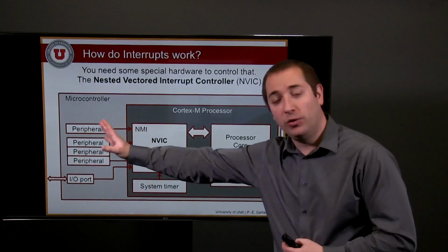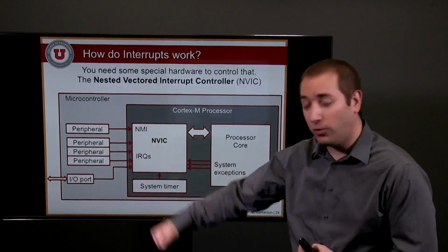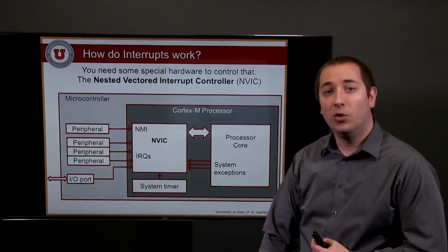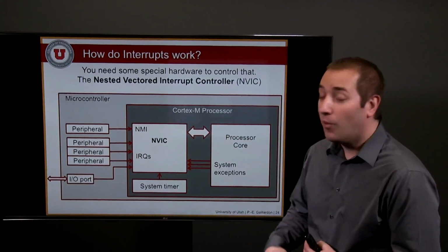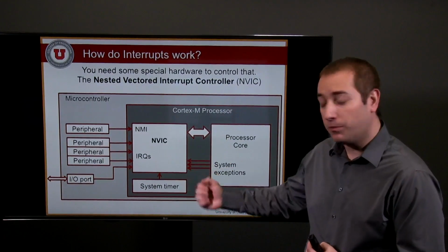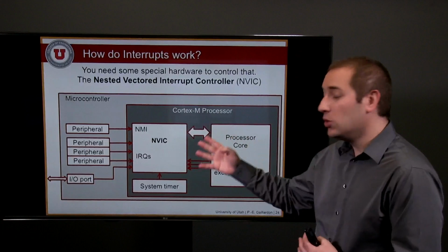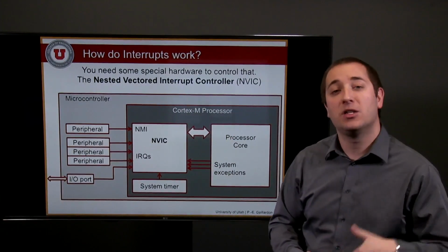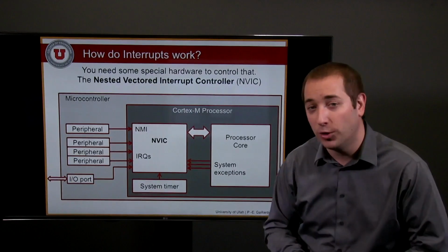It also interfaces with the peripherals of the microcontroller and basically aggregates all the interrupt request conditions and performs some arbitration. It also gets system exceptions, and decides which one should be processed first and to which part of the code the processor should jump.